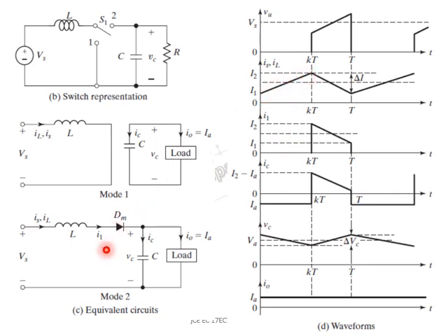And in mode 2, when the switch goes in this direction, that means this particular loop opens up and the diode is going to conduct here. S1 conducts and the load gets connected to the input supply. That means the load is now going to have this voltage at the output, from T on to T off. So this is the off time of the circuit in mode 2.